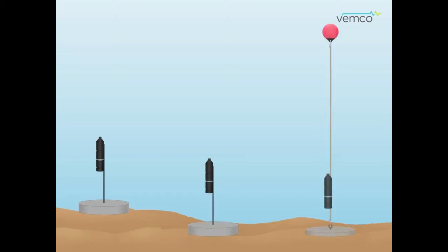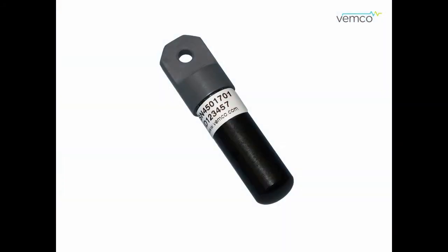But don't rush out and buy your tags yet. We suggest you use a range test tag during the range test. These tags are designed to be attached to a line and transmit at a fixed interval for easier data analysis. We can help you select the best size, power level, and transmitting interval for your test tag.